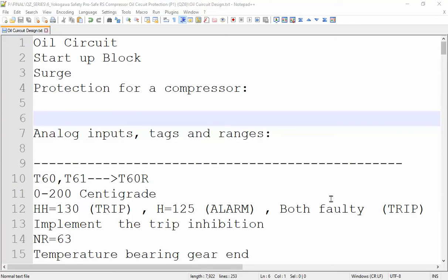So if you are in a remote area and you need some limited controls, even PID control, a safety PLC should be able to do that. The safety logic should be very small, but you don't want to make another cabinet for the control part. You can do all of them in the same solution.